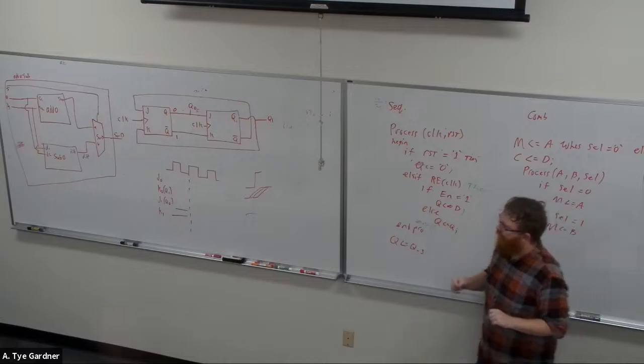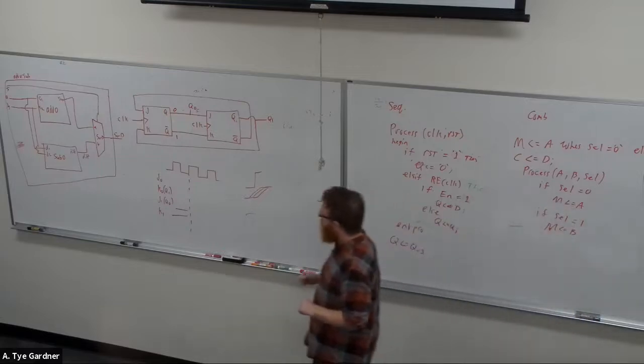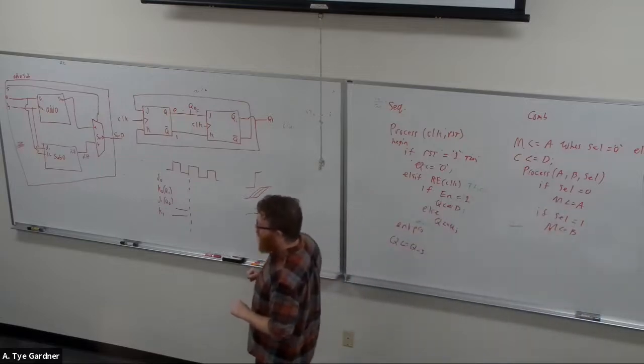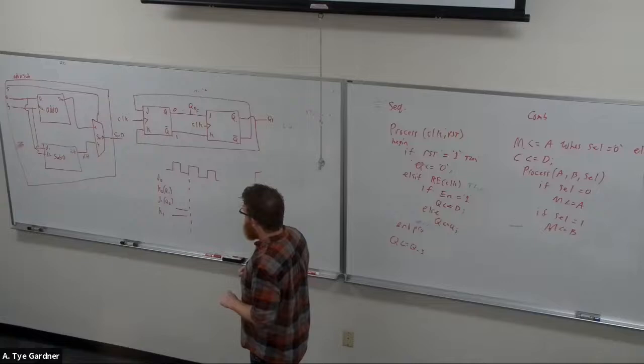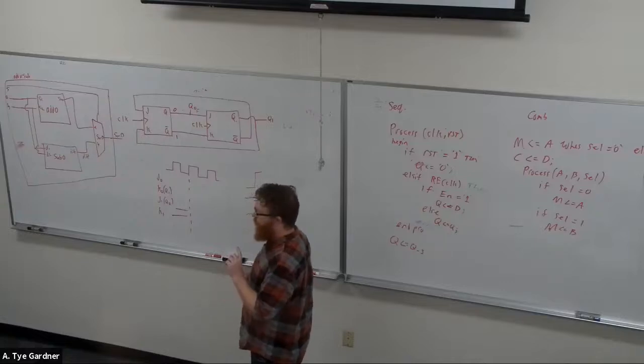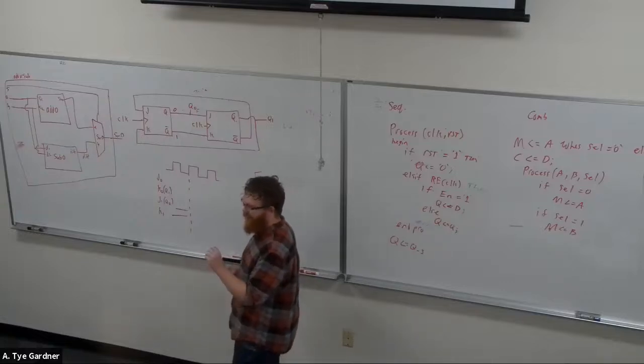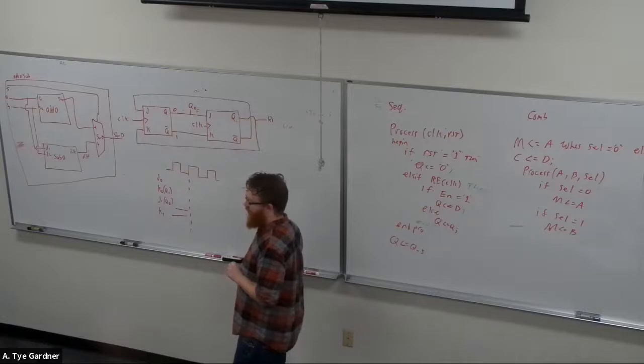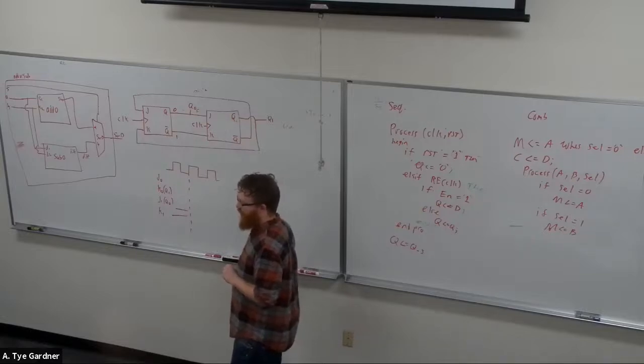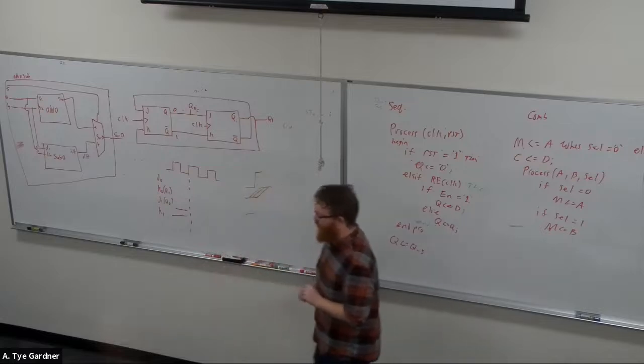That's just the cycle. When we do the timing diagrams, do you just want us to assume it's a perfect world and it does it right on that edge? You can't, because the toggle one won't even work if you do it right on the edge, because you don't know. Is it high or low right on the edge? Yeah, so give it a smidge of delay just because it will keep your life simpler.